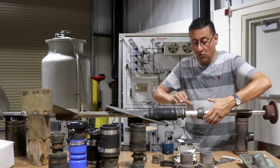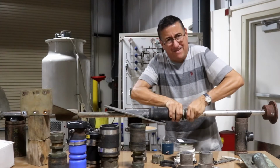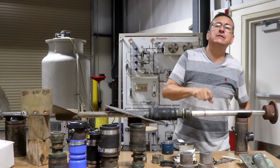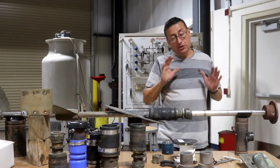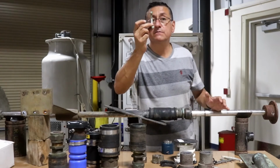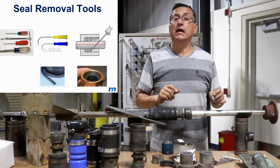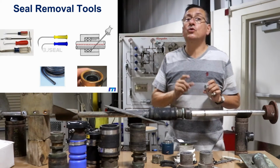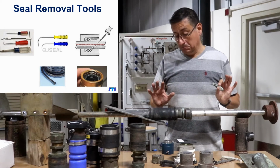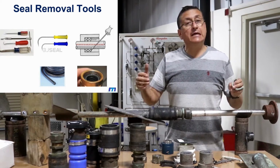After that, you start the process of tightening and tightening, and you verify that you don't have leaks. You need to be prepared with the seal and with the tools. Normally I use these types of tools to remove the old gaskets, and you need to verify that the bilge pumps are working properly, and that's it.